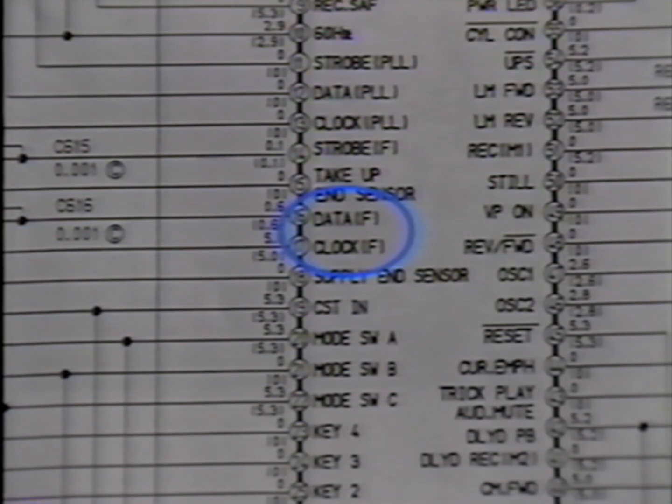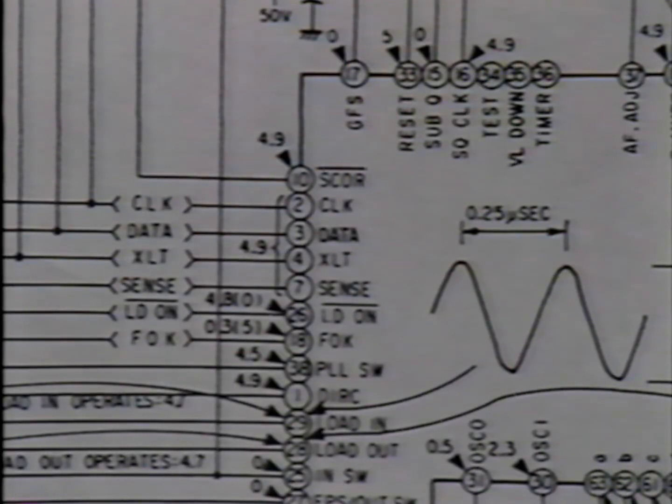Since each device only requires 3 output lines, this is a popular technique. Other system controllers, like the microprocessor in this CD player, use a single data line for all chips. All of the data output by the microprocessor is supplied to all of the chips.